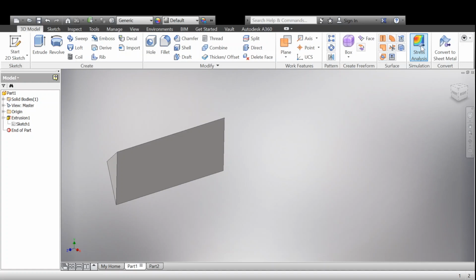Now, that also goes to say that your sketch from the first part here, if I go to click revolve, if I choose this revolve option, it says there's nothing there to revolve. So the sketch that you've used is all used up in a sense. This quadrilateral that's on the right side here is not going to be usable anymore. I cannot take this quadrilateral and do anything with it because this sketch already has been told to extrude only the triangular part.